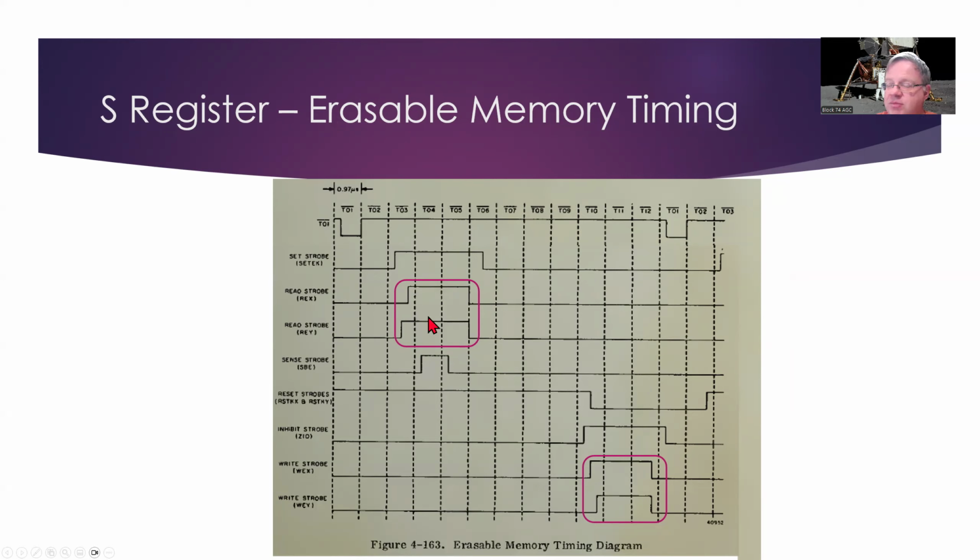So as we talked about, as we go through the sequence counter and we actually do the instruction decode, we run through these 12 timing pulses in order to take our sub instruction and decode it into the specific control pulses that actually have to occur in order to make that sub instruction work.